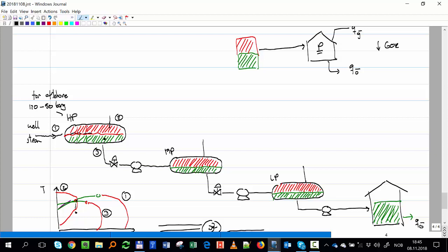What happens with that gas? It's exactly at the dew point. So if I lower the pressure a little bit, I will start having droplets of liquid, condensation. So I do two things. I put a cooler, just to try to drain a bit more from this so I won't have problems later. So I put a cooler. Then I use a scrubber.